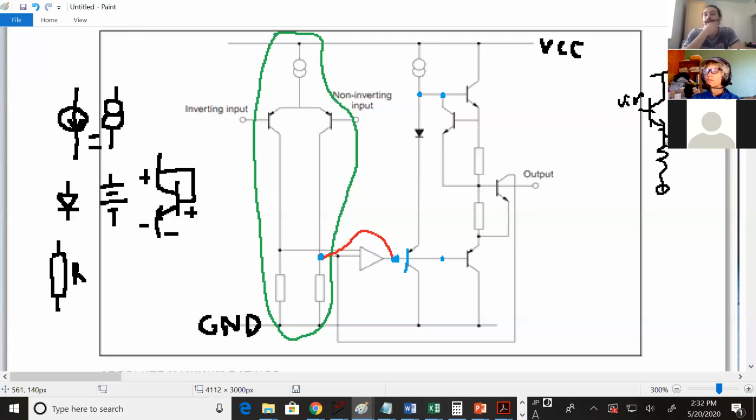Now you've got more current across your resistor, which means your VBE goes up and your V out goes back down a little bit. So because the current changes, the gain of your common collector is less than 1. So that's on the homework if anybody's not there yet.